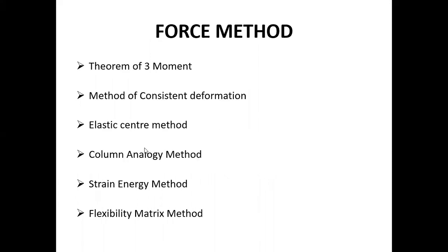Now we come to force methods. What are the basic force methods? The theorem of three moments, or moment area theorem, which we have already studied in Structural Analysis one. Method of consistent deformation, which we will discuss in the upcoming modules. The elastic center method is also used under the force method for the analysis of indeterminate structures.